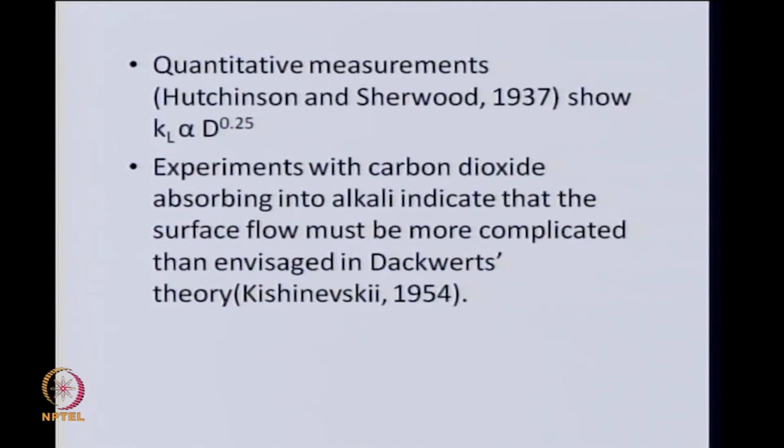So, with these closing words, I think I will be able to convey to you this much, that hydrodynamics plays a very important part in describing mass transfer in general, and as yet we do not understand it adequately to be able to predict mass transfer rates or mass transfer coefficients, absorption rates under all kinds of conditions from first principles.